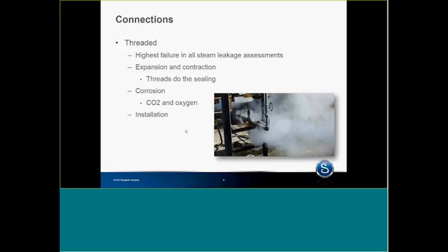The thing is that it comes down to installation. Why do we use threaded connections? We don't have to have a welder to do the welding. So it makes it a little bit easier, but it comes back to get us because we have so many steam leaks, which is causing a majority of issues. I gave up threaded pipe 24 years ago.